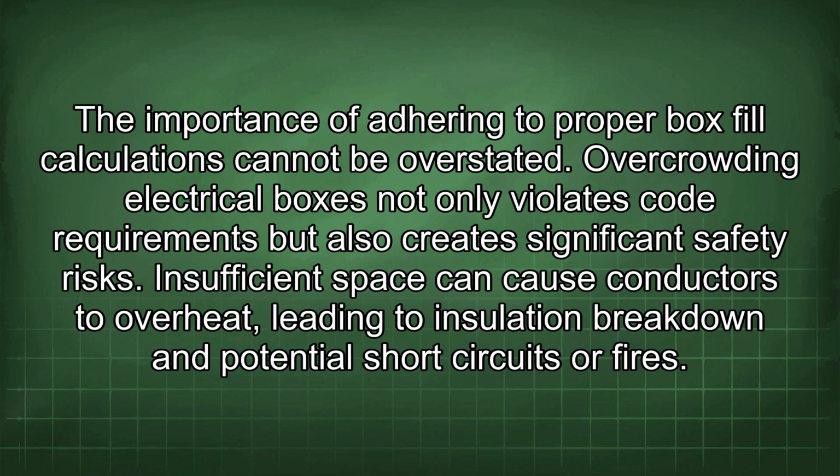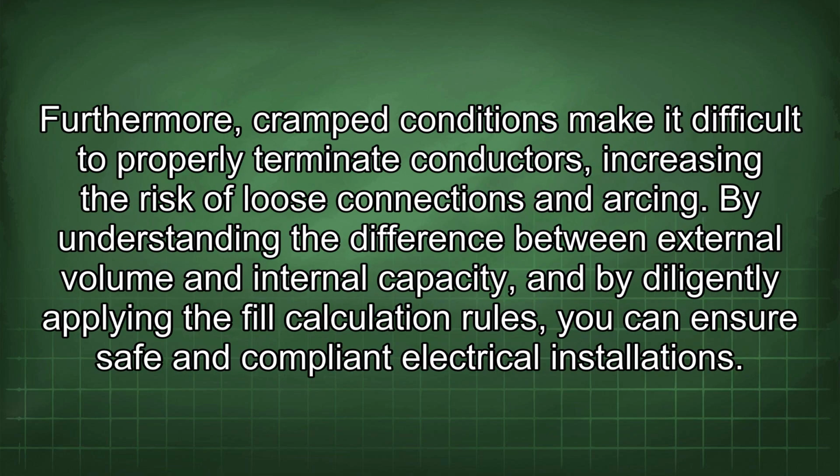The importance of adhering to proper box fill calculations cannot be overstated. Overcrowding electrical boxes not only violates code requirements, but also creates significant safety risks. Insufficient space can cause conductors to overheat, leading to insulation breakdown and potential short circuits or fires. Furthermore, cramped conditions make it difficult to properly terminate conductors, increasing the risk of loose connections and arcing.